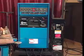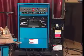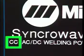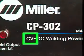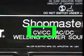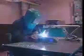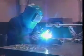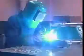Another characteristic that is sometimes used to distinguish between the various types of welding machines is the type of output that the welding machine produces. There are welding machines that deliver a constant current output, machines that deliver a constant voltage output, and machines that can deliver either a constant current output or a constant voltage output. Depending on the situation, each of these types of output has its advantages. Also, some situations require a particular type of output.